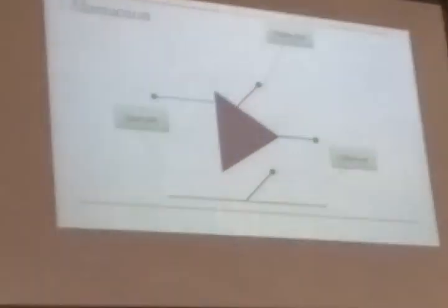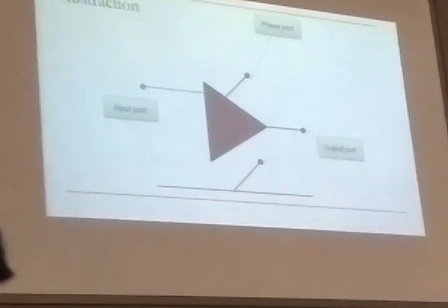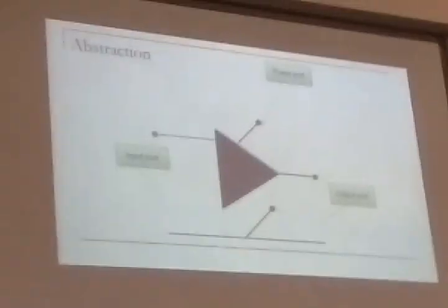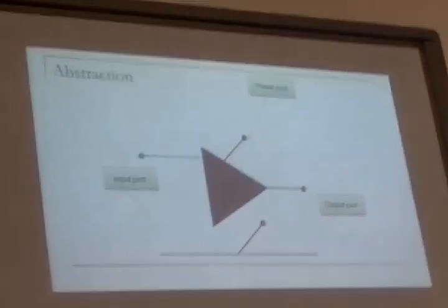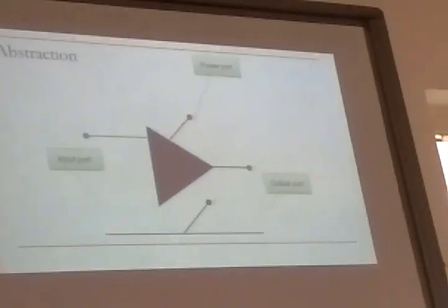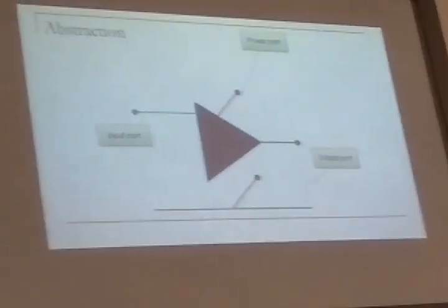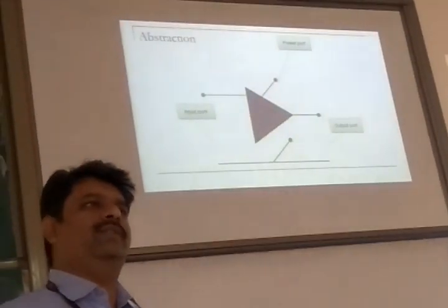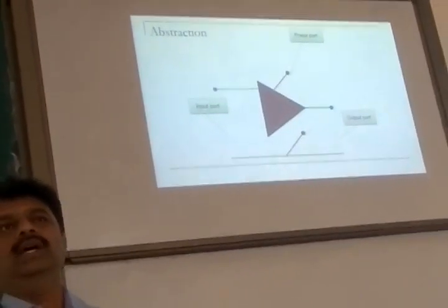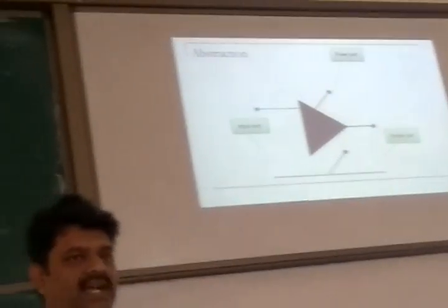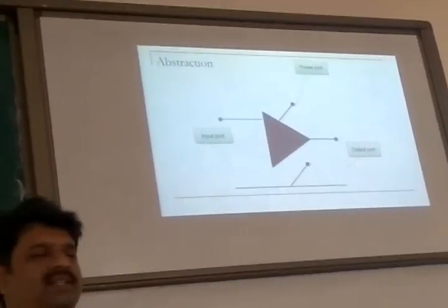You look for the data sheet. Oh, it is pin number 1 and 7. You connect 1 and 7. I am not saying this for a specific pin, but you have to look at the data sheet. One typical IC is the 741. 741 is an operational amplifier circuit. You take the 741 data sheet, and it will tell you this pin number is ground.